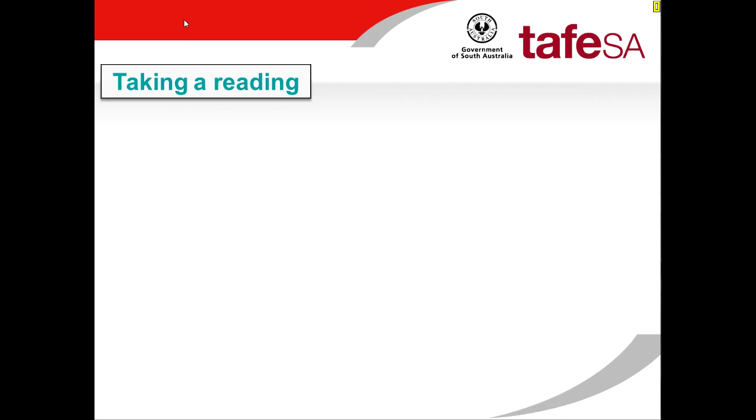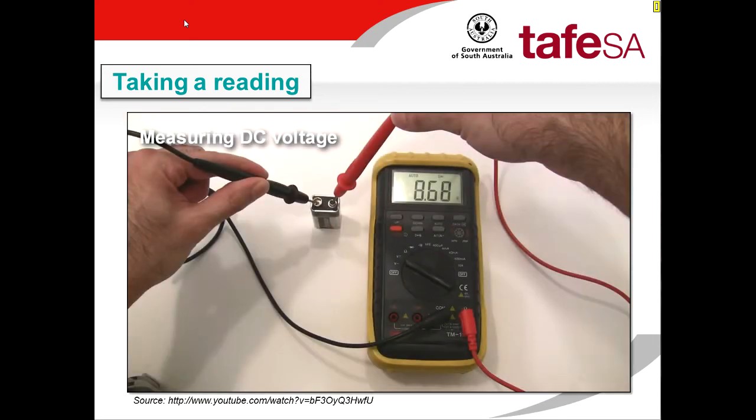Finally, we will look at how to take a reading. Taking a reading is very simple. All you must do is take the black and red probes of your multimeter and place them on the circuit where you would like to take the reading. In this example, we are taking a reading of a 9-volt battery. The black is in the negative terminal and the red is in the positive terminal, and you are taking a voltage reading. If you need help remembering how to connect your multimeter for each reading, just look back at the examples given previously.